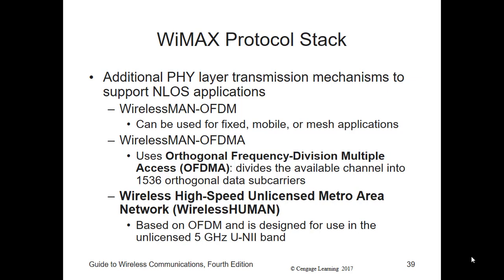In 802.16, the OFDMA is also scalable, meaning that the number of subcarriers allocated to an SS for the uplink can vary depending on the quality of service requirements, the signal quality, or the distance between the SS and the BS. However, to accommodate channel aggregation, which is multiple contiguous channels, in 802.16m, the number of UL and DL frames is fixed and asymmetric, meaning that there are more DL frames than UL frames.